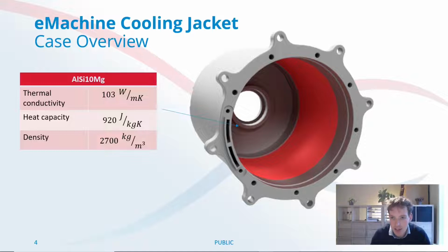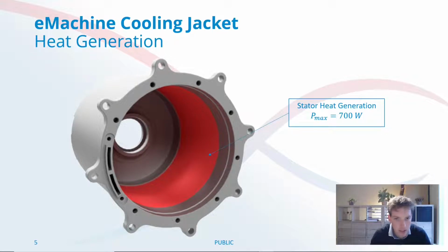The jacket itself is printed out of aluminum, and to be more precise, out of aluminum silicon 10 magnesium with a thermal conductivity of 103. The heat generation itself, as I said, is represented with a heated wall, and we apply a heat generation of 700 watts to this.